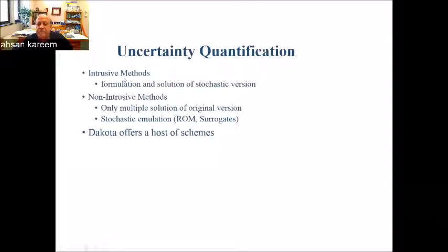There are some very sophisticated methods, which are called intrusive methods, in which your formulation has to be recast in a stochastic version. But I don't think this method is ready for the type of flows we are dealing with. So we have to use what we call non-intrusive methods. The simplest of them is Monte Carlo simulation. In this case, the Monte Carlo simulation will be 1,000 times your CFD run, which again is very challenging.